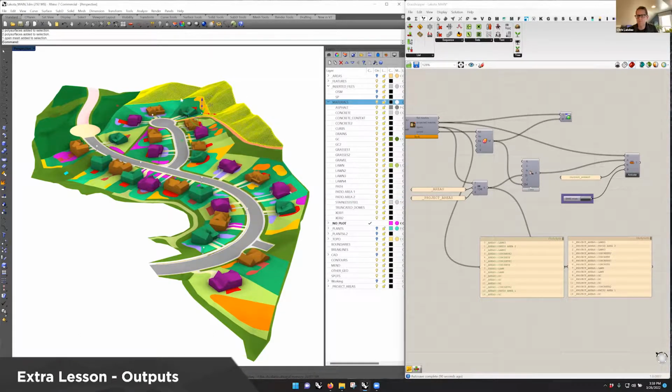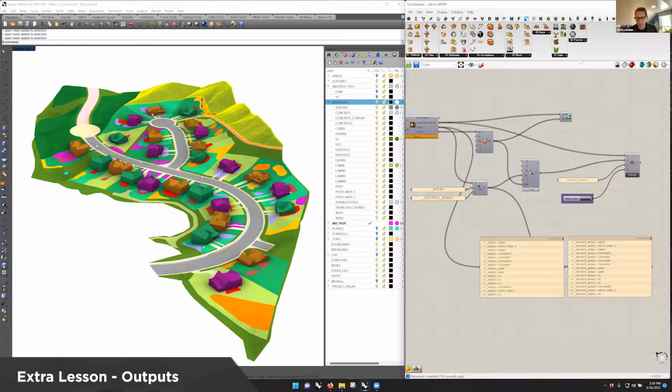None of these, there's only one mesh here. There's no longer 2 meshes because it deleted my meshes in the materials layer and replaced it with a mesh in this new layer structure that I've created, only because they have the same bake name. So that bake name, just pay close attention. It's like nitroglycerin. It can really move a lot of stuff at once, but you can blow some stuff up as well.